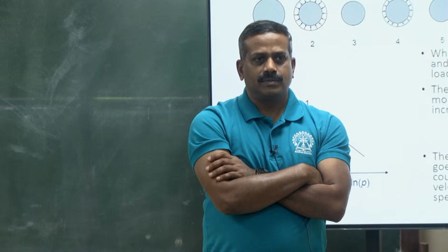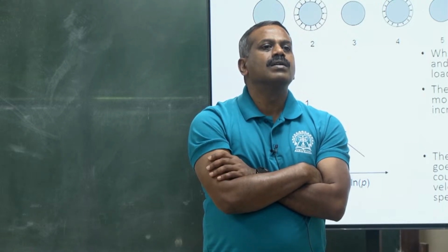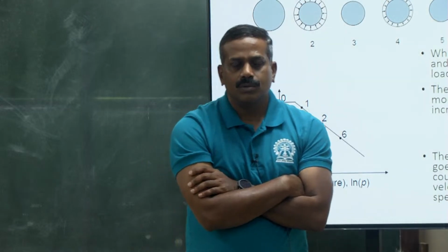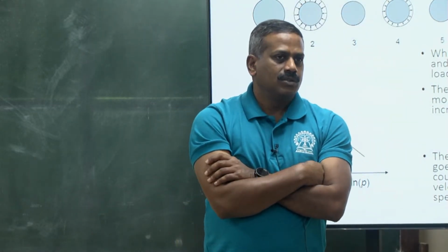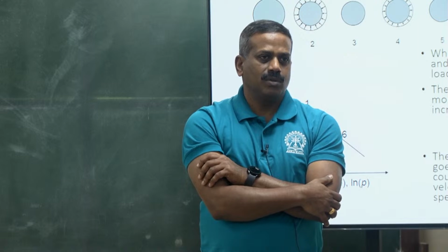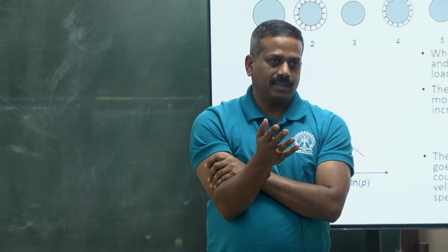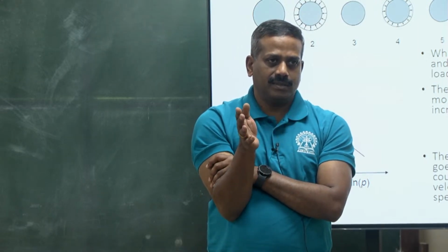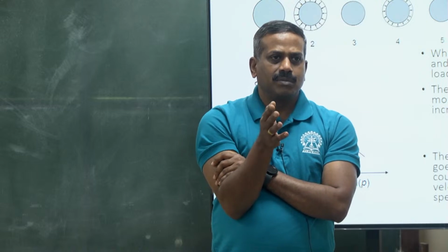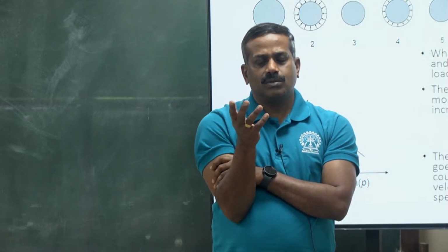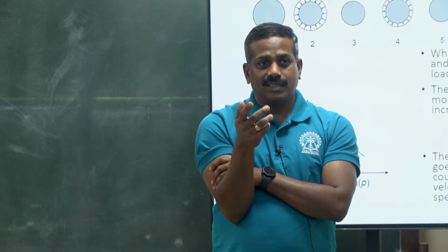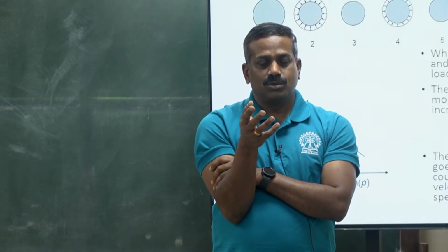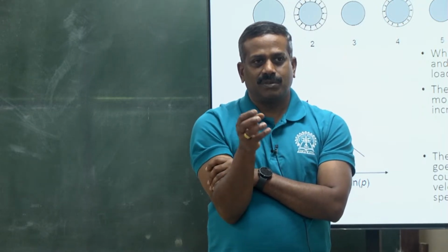Okay. So what other density can I measure for air classification? Particle density will be the one that gives you more information for separation of particles. It's very simple; you would have seen those winnowing machines, screen cleaners that are used to separate grains from chaff.